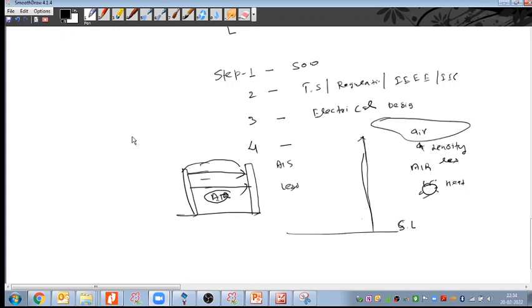You cannot dissipate the heat very easily. So if your cooling efficiency is less, the equipment is heated for more time, and then equipment performance will also be less. That is the reason that when we increase the installation height, the equipment is derated because of the air density. Heat cannot be easily dissipated into the environment because less air is available.